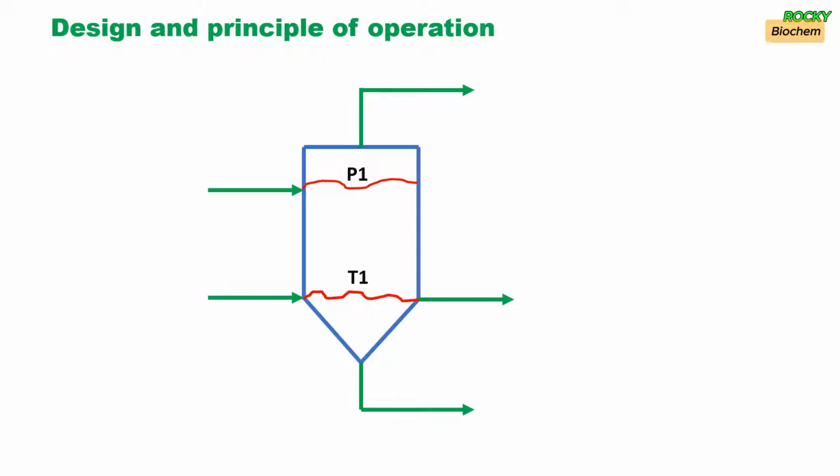So in such evaporator systems, the heat that is needed to evaporate the incoming raw material is supplied by burning of coal or any other heat source just to heat up the system. But with respect to a single effect evaporator system, we specially design this system in such a way that the heat needed to evaporate the incoming feed is supplied by steam that is also fed into the chamber. So the entry points are meant for both the feed and then the steam. The feed enters through one compartment and then the steam also enters through the other compartment.